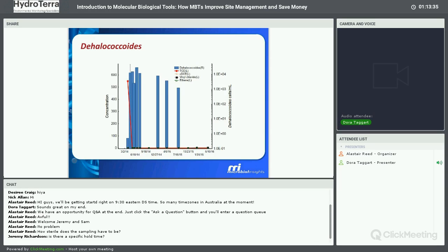But what about biodegradation? After injection of the activated carbon, biostimulation with an electron donor, and bioaugmentation, the Dehalococcoides concentrations went up to greater than 10 to the 4 cells per mL, that critical concentration that we want for effective biodegradation. Dehalococcoides was even maintained at greater than that number for almost 9 months, even after the removal of the chlorinated hydrocarbons from the dissolved phase.